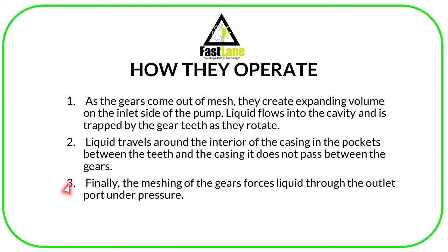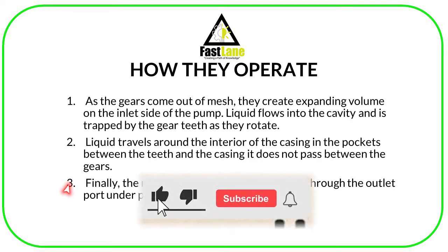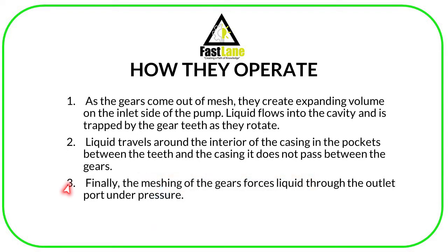The disadvantage of these pumps is that no solids are allowed. Since these gears come into mesh with each other, if solids are used, you'll find that the solid will be damaged, right? So fluids are the only ones used in these pumps.